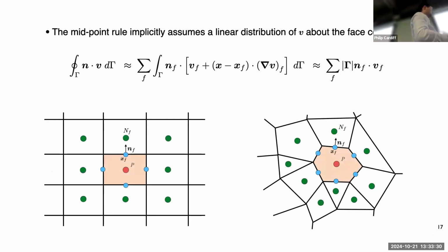So that means if I'm on a structured grid like this, I will just sum over each of these faces. If I go to this face to evaluate this term at the face, I can just get the velocity at that face multiplied by that normal, and then multiply that by the magnitude of the area vector here, and then just sum that term up for all 4 faces.